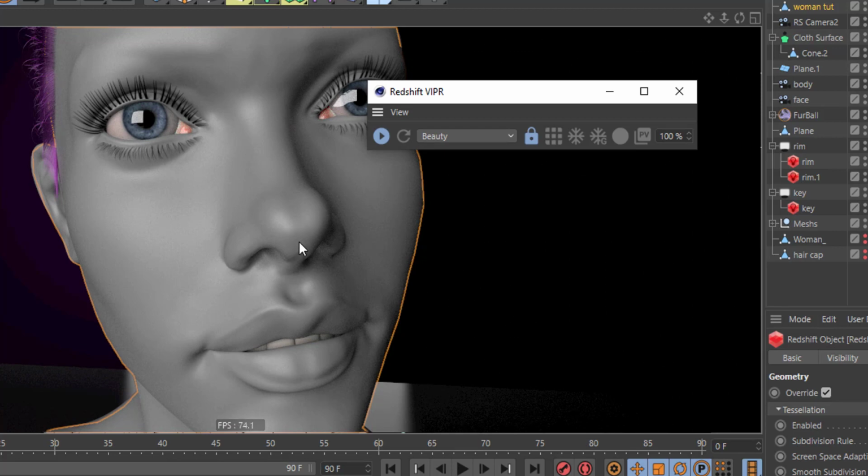Now I intentionally disabled a layer inside Zbrush, and the layer that I disabled was the high frequency detail. The reason why I do this, and it's not mandatory that you do this, is because I like to have the detail in a separate displacement map. This means that I can use the displacement blender to dial in the strength of the detail separate from the displacement itself. It's nice to be able to have that kind of level of control.